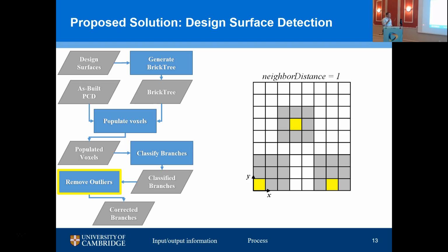So there are two parameters that we played around with there, and this is in the journal paper that's going into review soon, so it wasn't in the conference paper. The two parameters are the neighbor distance, how far do I search around that raster branch, and then the consensus threshold. Is it 50%? Is it 60%? Where do I draw that line to say if 60% was base course, then this cell should be base course as well?